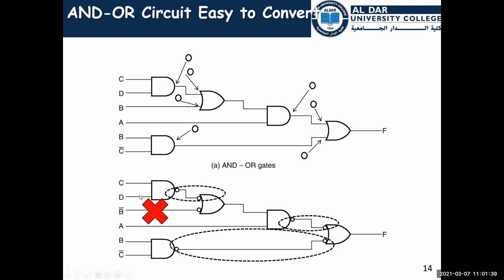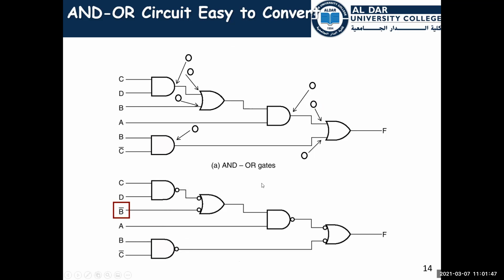So this place has a problem, as I told you, and you have to solve it using a converter. He just said that B should be B dash. This means it should be converted. That's it. He didn't say we have a NAND gate and we attach the two inputs of the NAND gate together to have an inverter, but he just simplified it and said this is complemented. B dash is complemented.